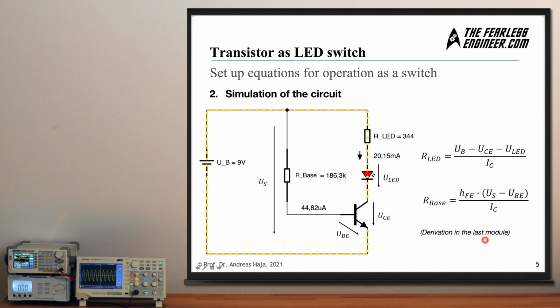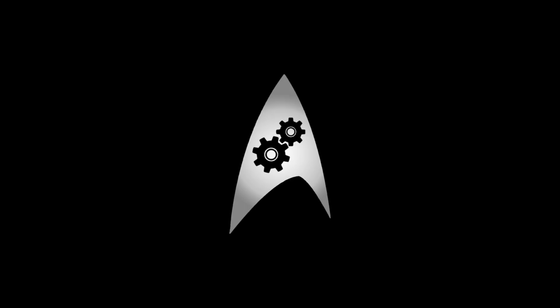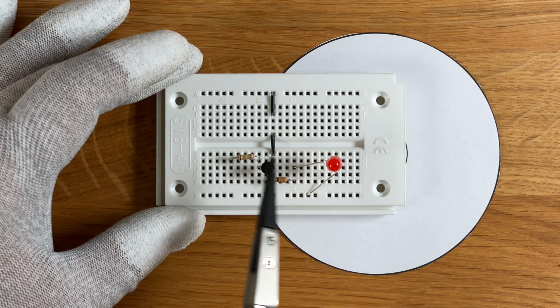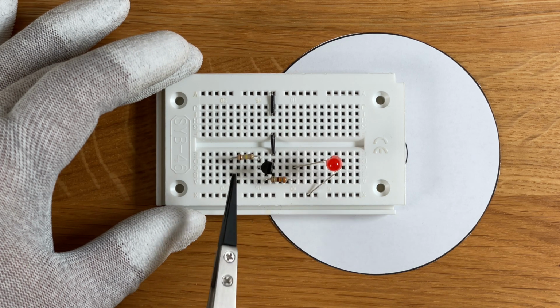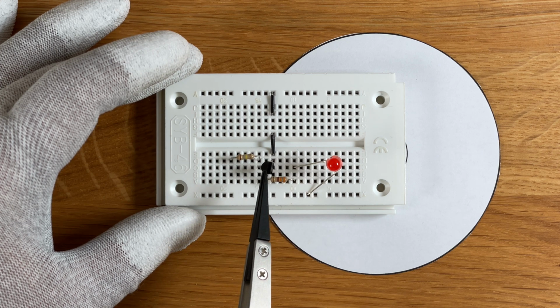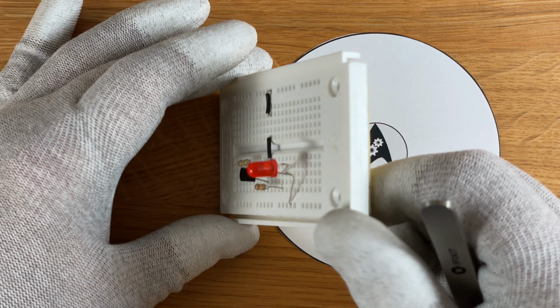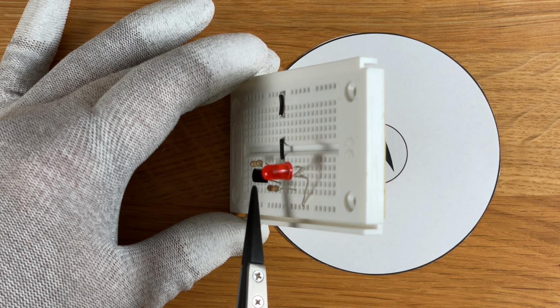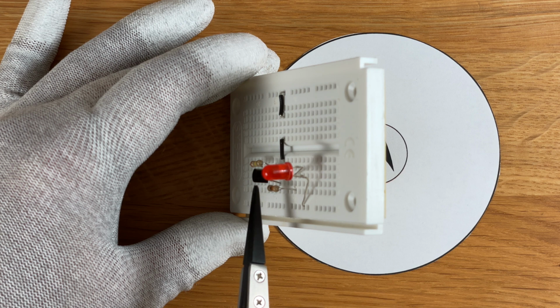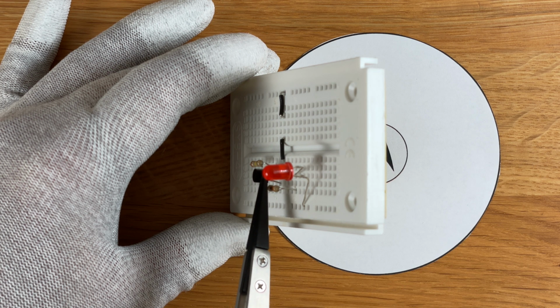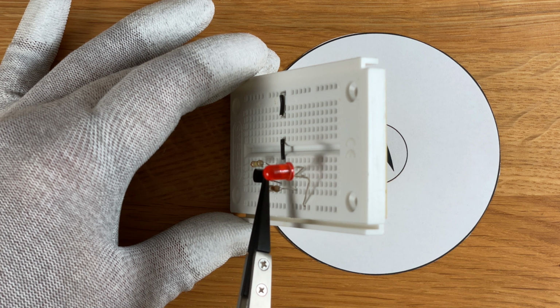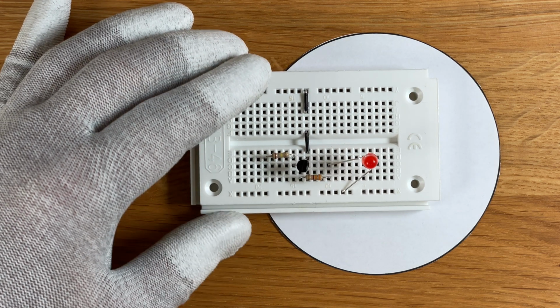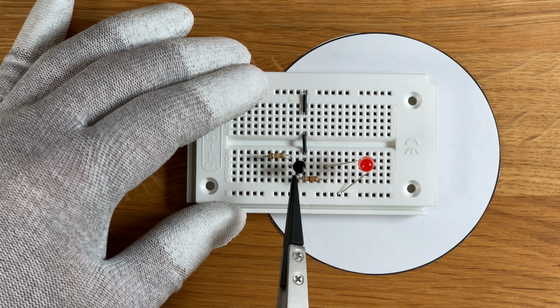And what I want to do now is I want to construct the same circuit here in an actual laboratory setup. So let's head over there. Let's take a look at the circuit as we have seen it before in the simulation. The heart of everything is the transistor, which you can see here. If you take a very close look, it's hard to see in the light, but if you take a very close look on the housing, it says BC547B. Also, there's a small e in the lower right corner here, and this tells us which data sheet to fetch in order to extract the parameters from.